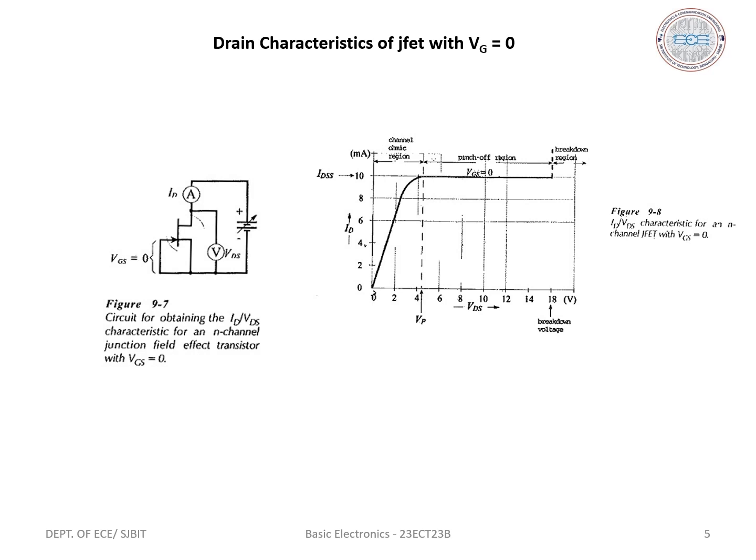The channel behaves as a fixed value resistance until the voltage drop along the channel causes penetration of the depletion region into the channel and channel resistance becomes high. Further increase in VDS gives a smaller increase in ID and causes more depletion region penetration with a high channel resistance.